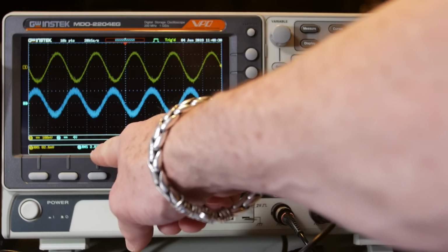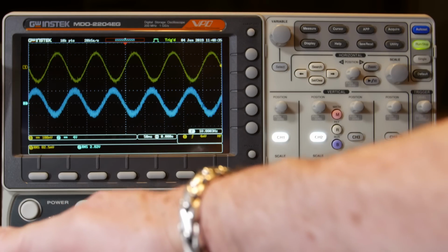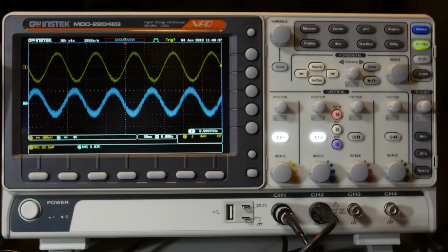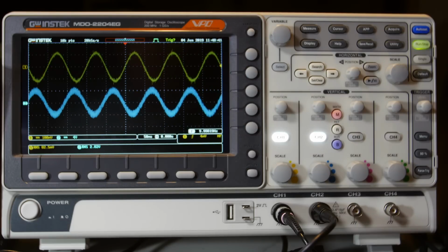That would be V squared over R. So it'd be 3 times 3 is 9 over 8 ohms. Would be a little over a watt. But since this is below 3 volts, it's probably close to a watt or a little bit less.